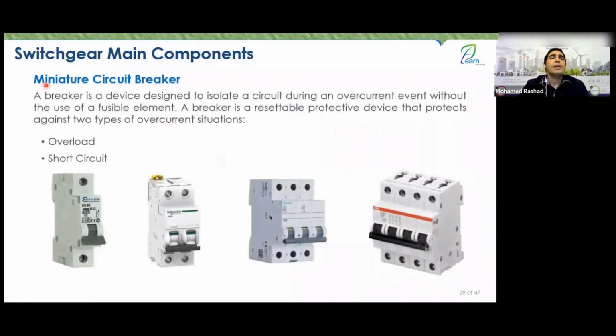Now let's move on to the miniature circuit breaker, which is mini. It refers to a miniature circuit breaker. The miniature circuit breaker will be installed, and this is not a fuse. Its purpose is the same as the large circuit breaker. The large circuit breaker is used for switching and connection as control or automation and as protection in case of a short circuit. The same applies here. It's a circuit breaker, but smaller. It is used for switching and connection, but specifically for the control circuits in my cell. And it also provides protection in case of a short circuit.